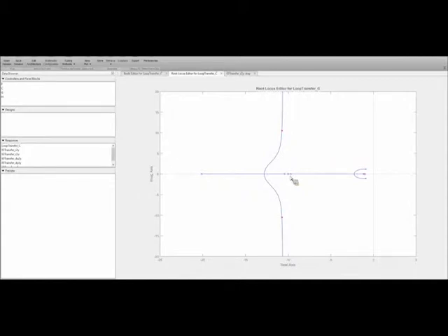We have essentially a pole zero cancellation here, and we have a pole zero cancellation here. And so these are dynamics that are not really appreciably affecting our system. The system is acting like these 2 poles here and here for the most part, right? Because these are the ones that don't have a pole zero cancellation. They're fairly close to the origin. These are being canceled. So the dominant dynamics of the system are somewhere on the order of natural frequencies of 10, right?